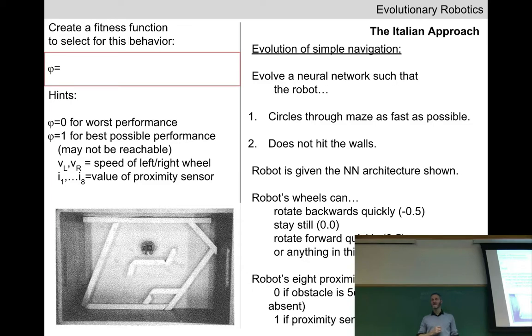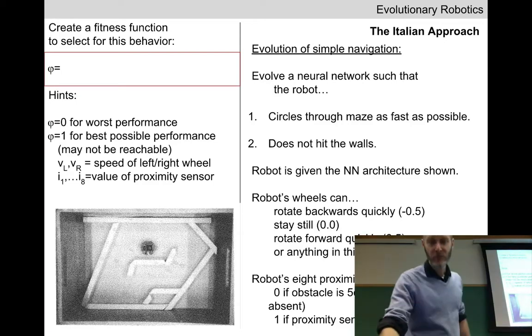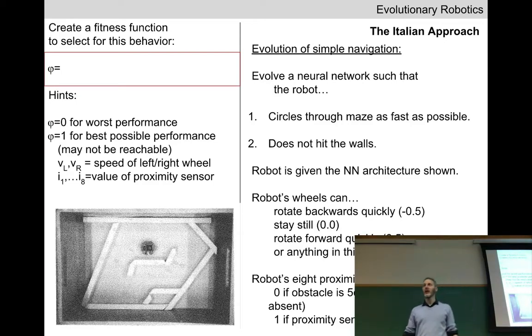We could continually ramp up the motors VL, VR while making sure that the robot turns away from the sort of, if the first half of the array is activated, turn away from that. The right half of the array, meaning sort of like 4 through 7 or 4 through 8, turn away from that direction. Okay, that sounds good. We could try that.